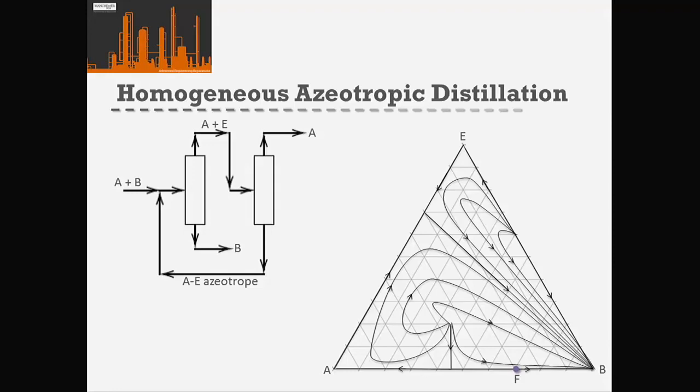But unfortunately, that forms an azeotrope with our A. And we also have this other interaction with both our components to form a ternary azeotrope. So it adds to the complexity that we now have these two distillation boundaries within our system, but can we still design a system that we can use?